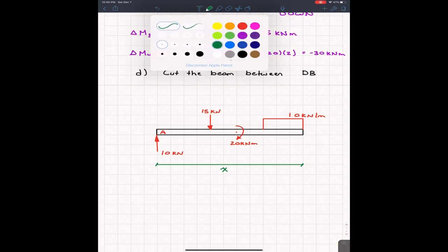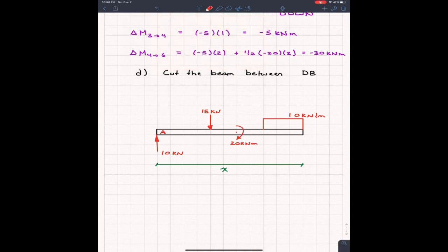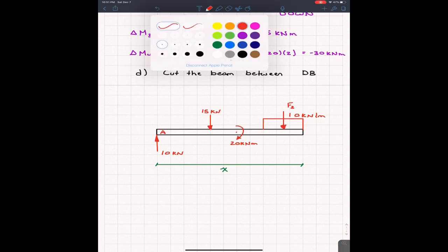And since we're now taking loads at a single point, remember, if we're taking loads at a point, then we can replace the distributed load with a point load, and we're going to call this one F2. So these were all my external forces that I knew from before. The only difference now is they're at distance X. We have to find out that new distance.